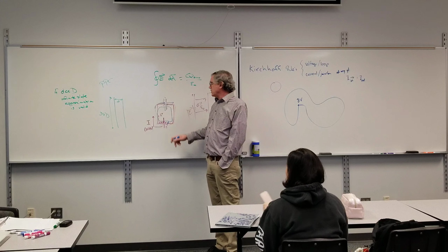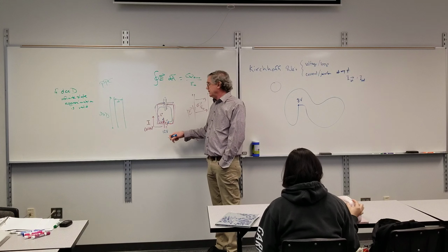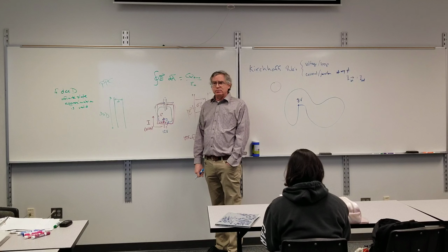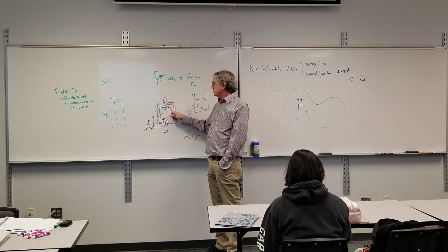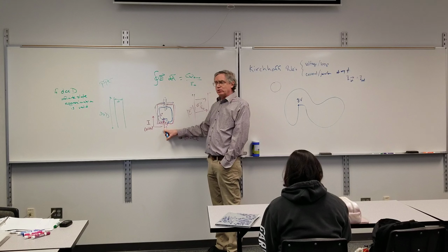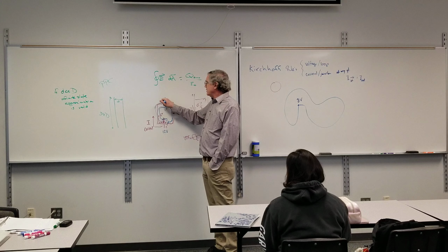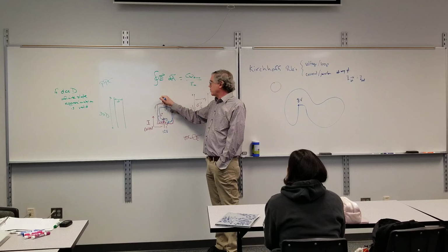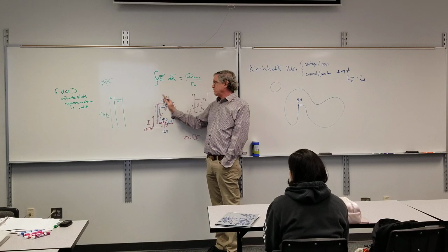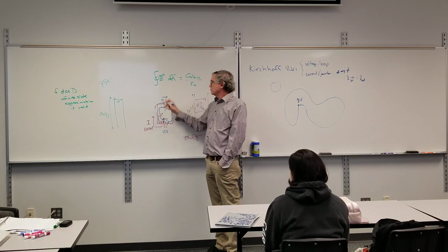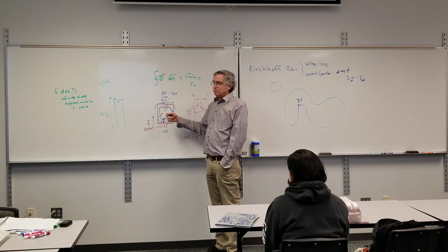So if I look at this battery hooked up to here, if this is a 12-volt battery and I'm going from the negative to the positive side, I gain 12 volts. I cruise along, I cross over my capacitor, come back, I should be at 0. So if I gain 12 volts here, I have to lose 12 volts there. Also supporting the idea that this is the positive and that's the negative side is because if I'm going this way across it, I have to lose 12 volts. In other words, the voltage across here, going from left to right, would be negative 12 volts. Going in that direction, negative 12 volts. Going in that direction, positive 12 volts.